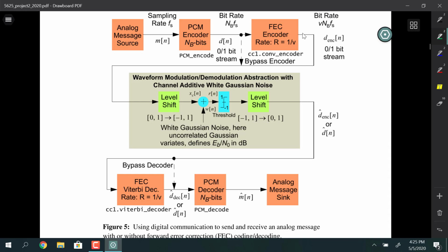But the convolutional code that's used here is so powerful that it gets you back all of that and then some. So the main point will be to listen to it with the 6 dB channel Eb/N0, or SNR in the channel, so a very poor quality channel, versus one that's not protected, and it'll be an amazing difference. It's striking.